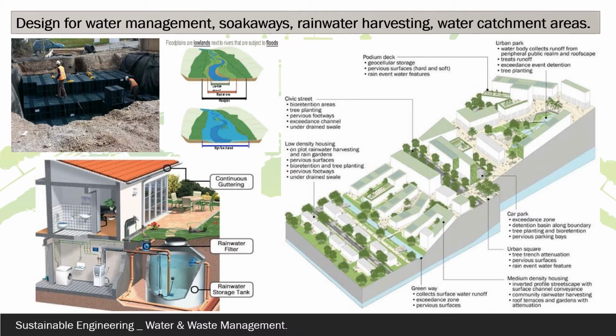If we design the infrastructure in a way that it doesn't sit in the impact zones, then we'll know that these areas can naturally flood without having to affect the buildings around them. But also within each individual building there are things we can do to reduce the amount of water supply. We can build in rainwater harvesting tanks on our sites so that water can be filtered back into our toilets and other non-essential services to be able to recycle that water. It can be captured in our gutters and fed down into it and then connected to a soakaway for any overflow water to be dealt with.